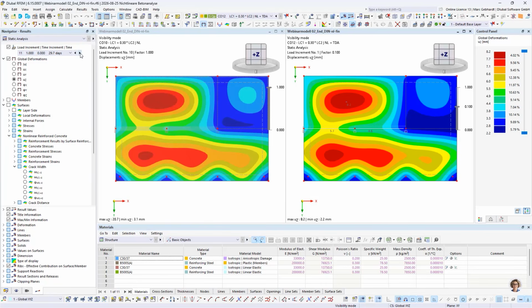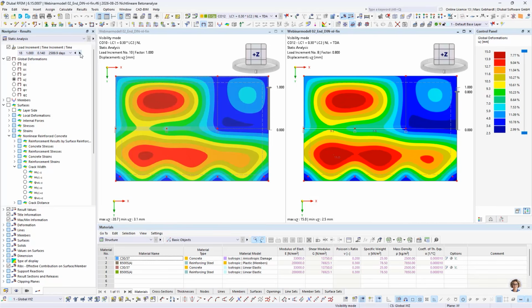So go there and see the deformation getting higher and higher until 50 years are reached. You see here the maximum deformation is 18.9 millimeters. Also, we can see that we have another distribution on the surface. This is caused by a different combination between the beam, the ribs, and the outer surfaces and the columns beneath these. So we have a realistic, nonlinear, time-dependent behavior.